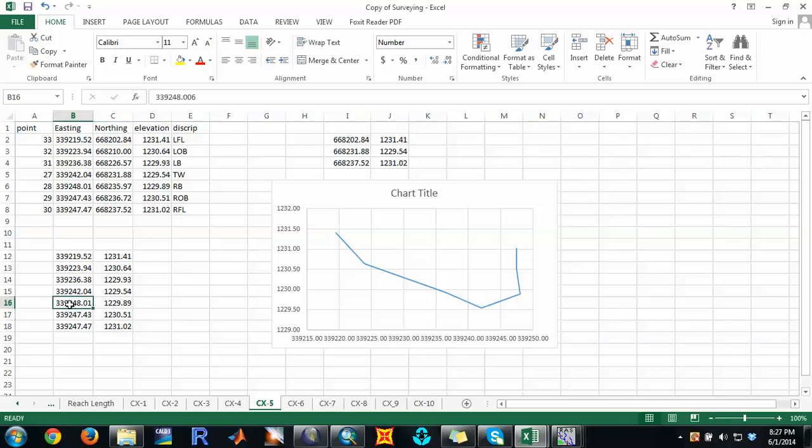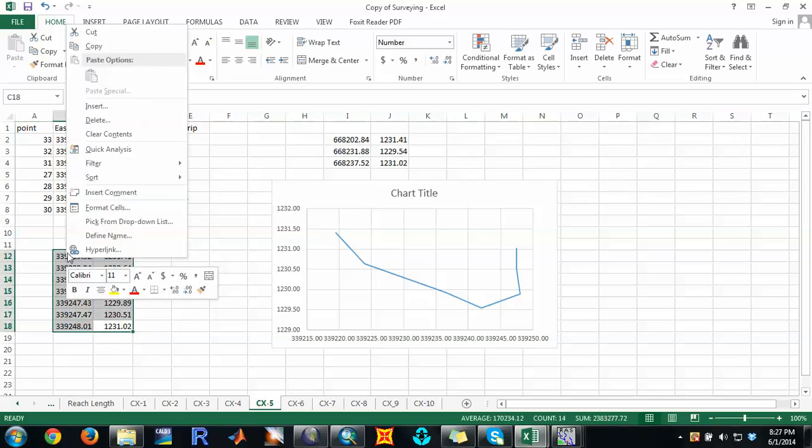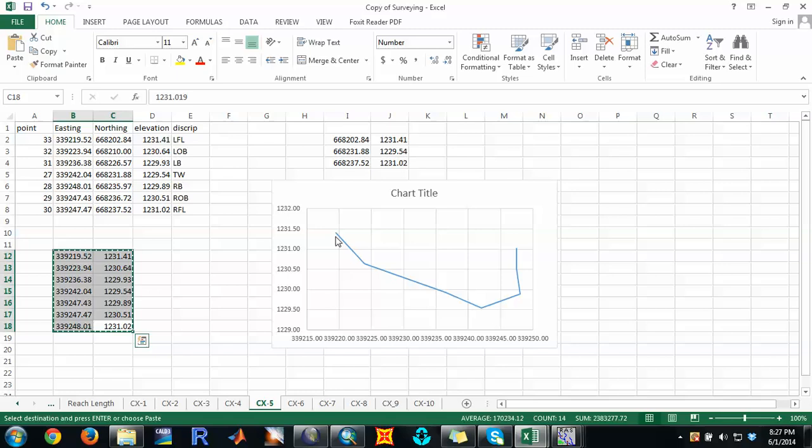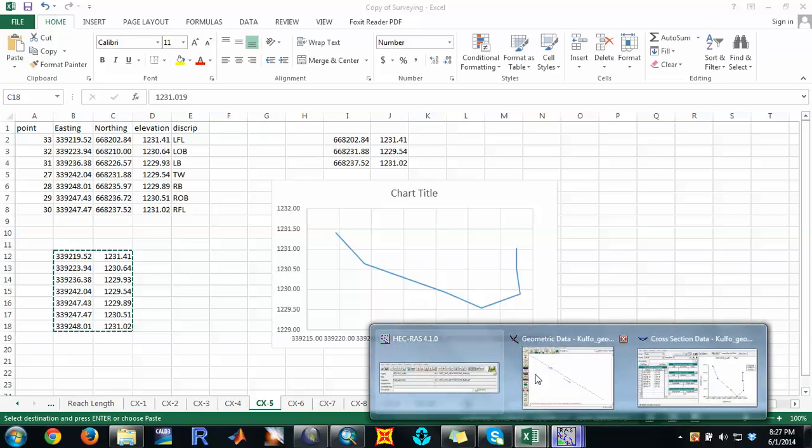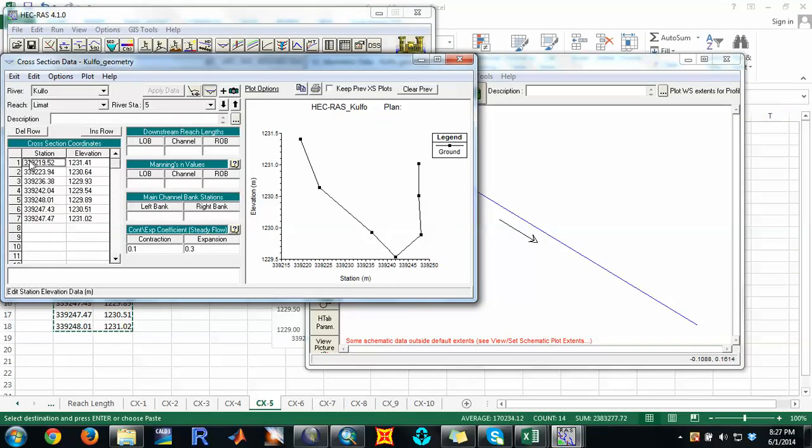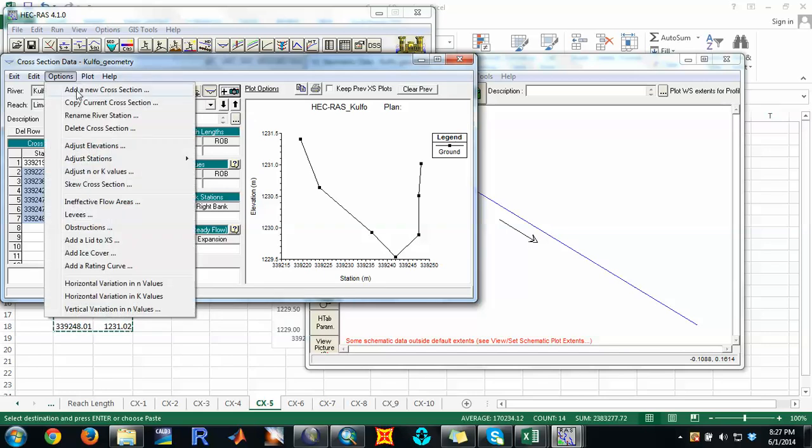So we have to leave the elevation as it is and correct this one, because it should be at the end of the data, and now it is okay. Because as you go from one cross section to the other bank, there must be an increase in the x-axis. There is no deformed shape of a river. So you can come to cross section back and change this data. Okay, and let's try it again. So it is good now. It is corrected.